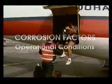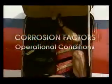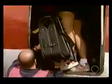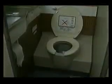Operating conditions can also create an increased corrosion potential on your aircraft. By operating conditions, we mean problems associated with routine use or misuse of the aircraft. These factors include any type of spillage, either of a chemical or of spills in the lavatory or galley areas of the aircraft. Both of these places are classic breeding grounds for corrosion.